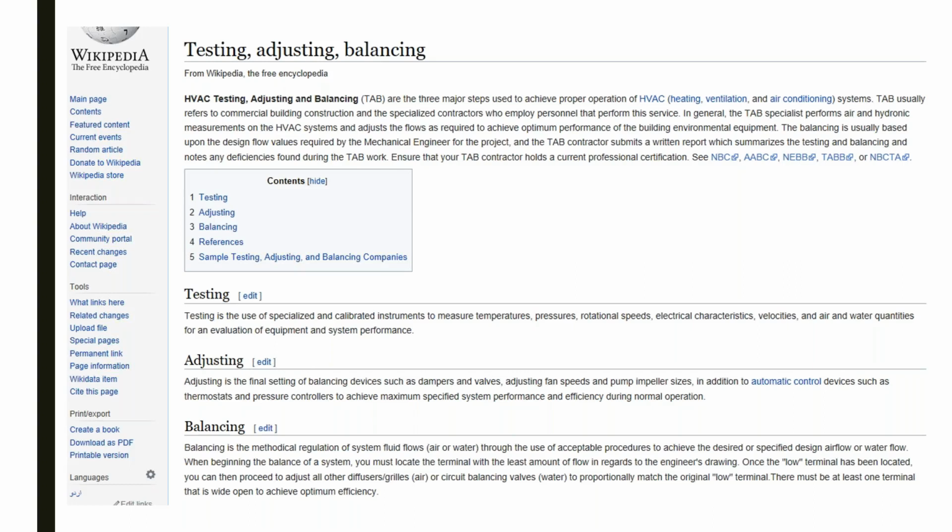But this is DX equipment, so the DX equipment runs either on or off, and the slowing down of the airflow meant that it had to run longer to cool the space because we're not moving the right amount of air. So even though I increase the speed of the fans to use more fan energy, I now decrease the DX cooling requirements to where I don't have to run it as much. But it's deferred maintenance. They need to get in there and replace all those drive sheaves.